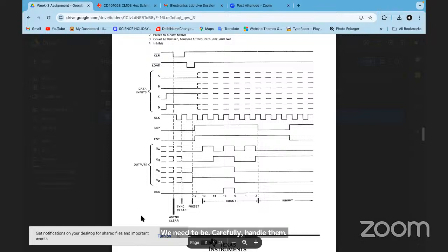So, another thing I found is that it is around 1 volt. There is quite a lot of glitch on all transitions. Is it because of the hardware or the firmware or the driver? We don't know. But what exactly is happening is that you have introduced a mid trigger because of the hysteresis, not because of the current driving capacity. It is because of the hysteresis involved. We are able to get away from it.